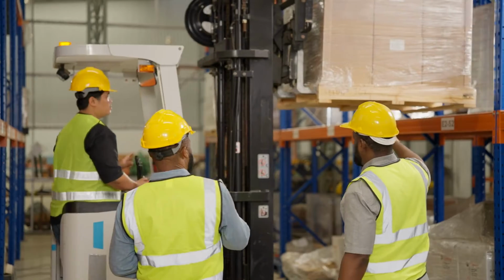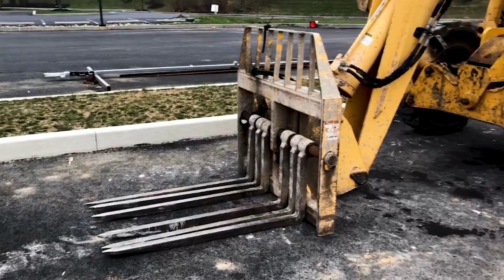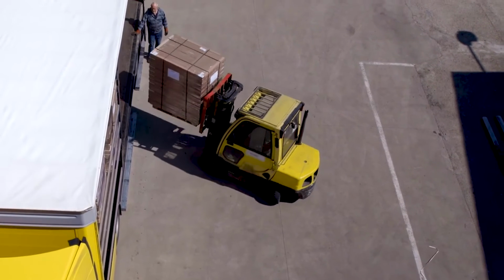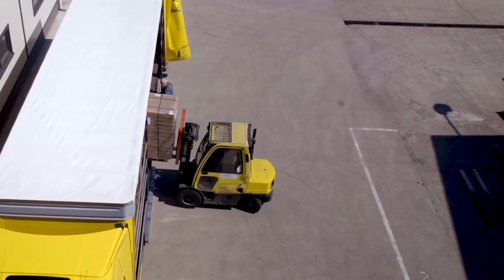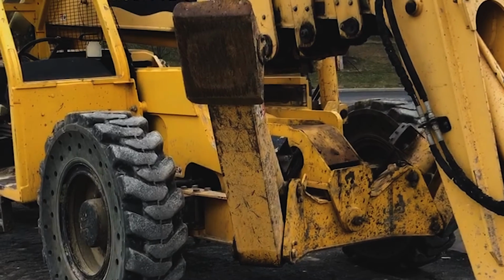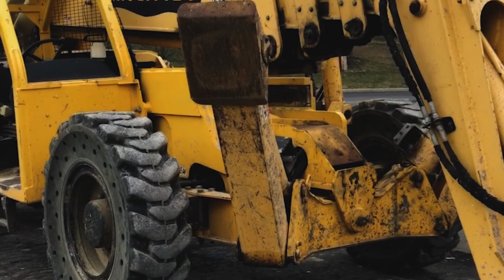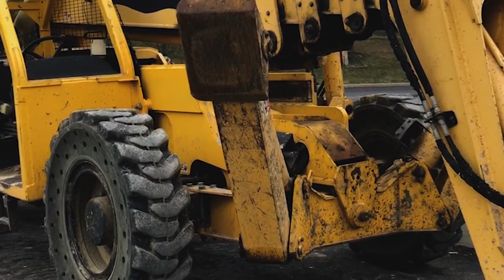While these principles apply mainly to standard forklift dynamics, it's worth noting that specialized configurations like reach trucks, side loaders, and telescopic handler forklifts might require slightly different applications of the same physical principles. For example, a lot of forklifts include counterweights at the back to help maintain the center of gravity within the stability triangle. But some forklifts broaden the stability triangle using extended legs called outriggers.